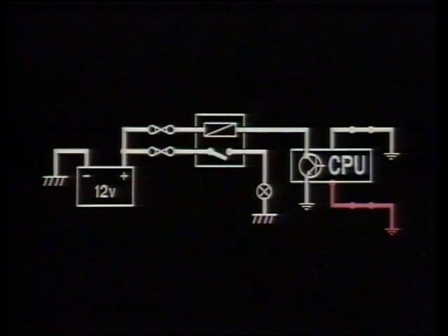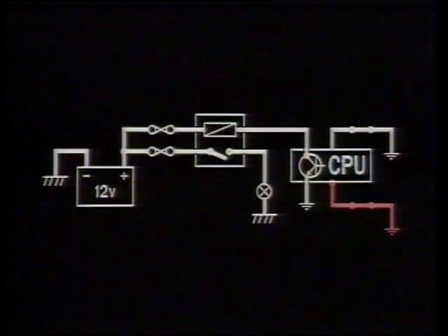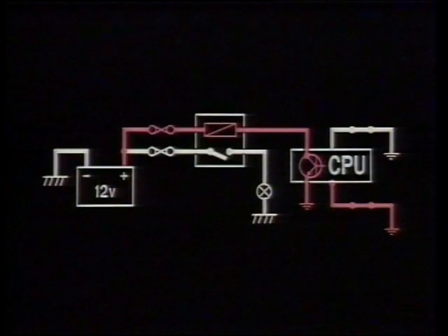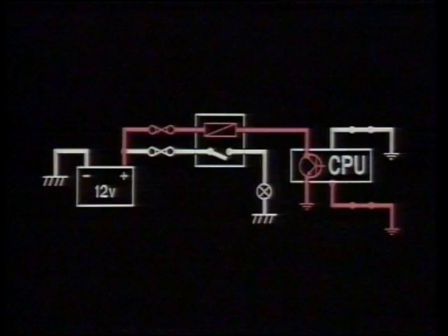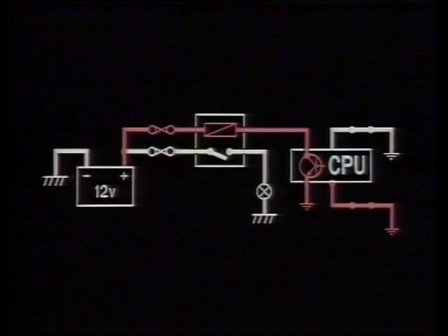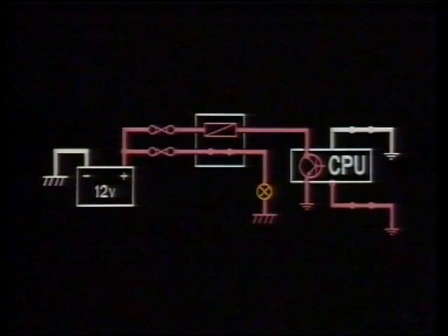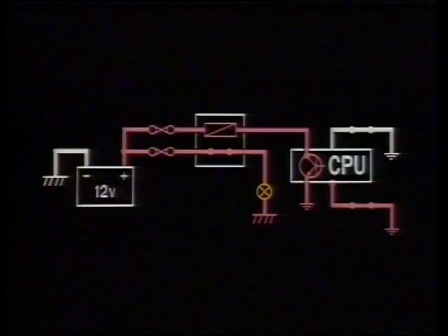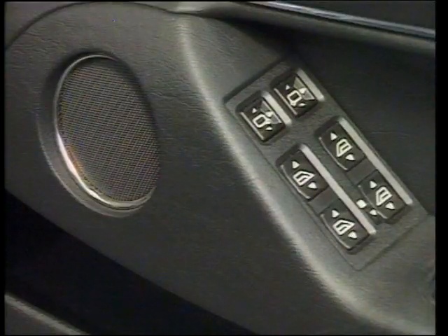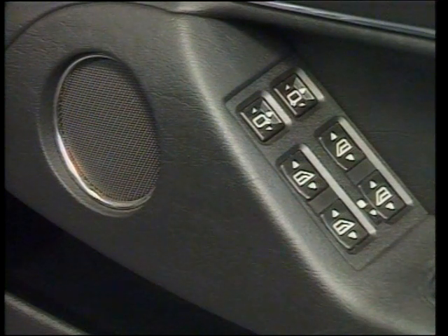The CPU detects an input and responds by sending a minute current to the transistor to switch it on, which will allow current to flow through the relay windings, through the transistor, and down to the logic earth, thereby energizing the relay windings. This will close the relay contacts, allowing 12 volts to pass through the bulb to the power earth. In circuits of this type, the driver's switch need only be small, like a momentary action clicker plate switch.